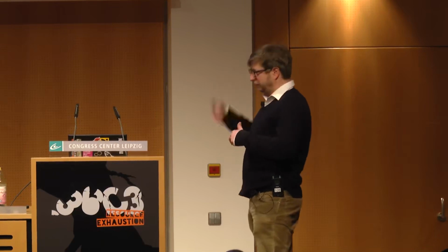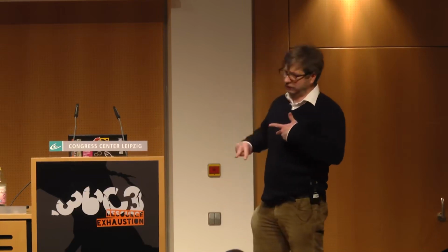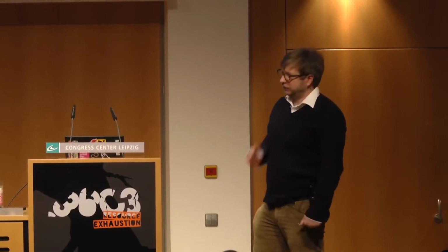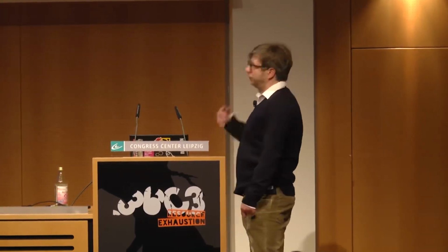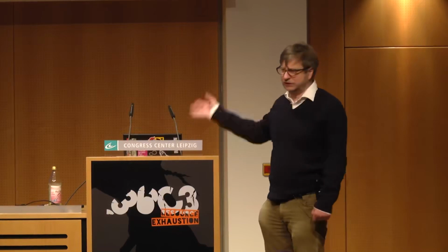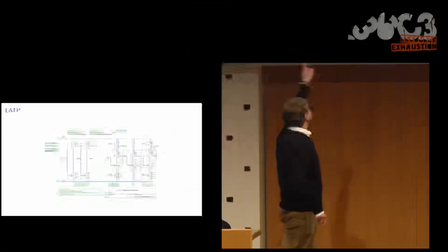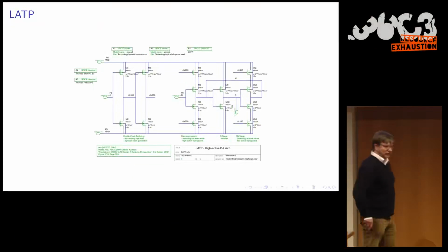The first one is transparent at the falling edge, but the second one is then not transparent, and so it becomes only usable on the rising edge of the clock. So latches work only when the input is on, and flip-flops are triggered by the rising clock edge. That's the difference. Now back to the slide.